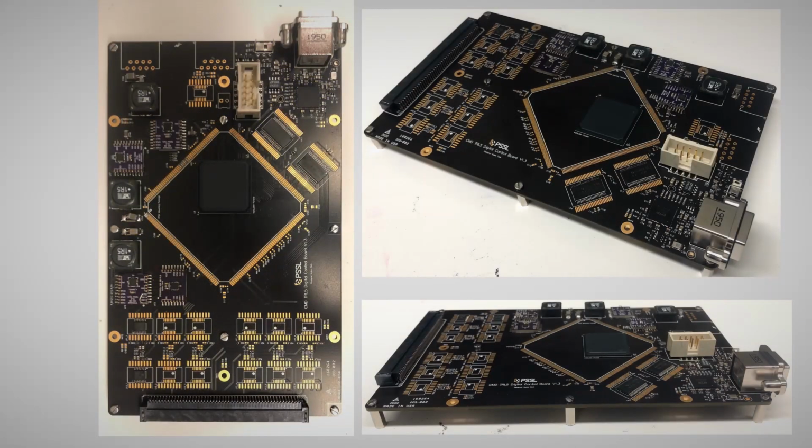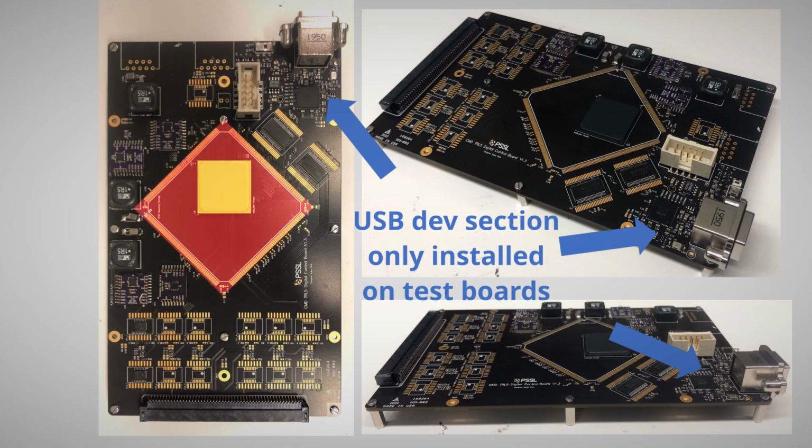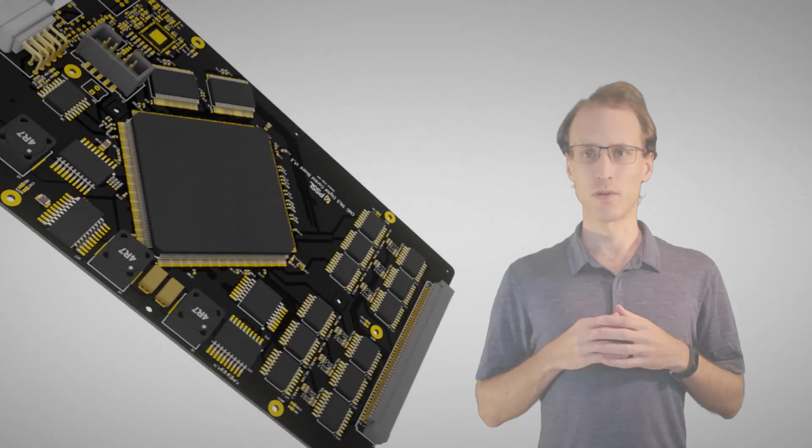Now, the current DCB doesn't quite look like the design here, for a couple of reasons. The first is that it's still under testing. Currently, the firmware is being completed to bring it all online bit by bit. The other reason is that the space-qualified FPGA is really expensive. So, to reduce our collective anxieties, a firmware-compatible commercial off-the-shelf version is being used during development. The board is designed to be operational with either being soldered in. Okay, now let's get back to it.